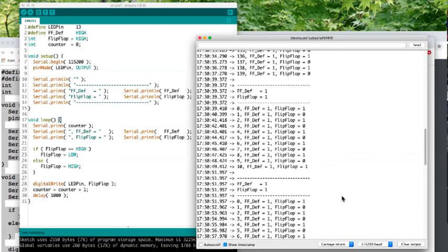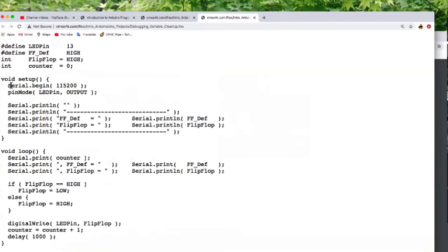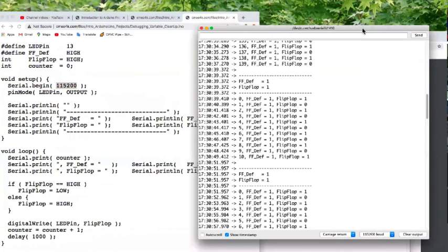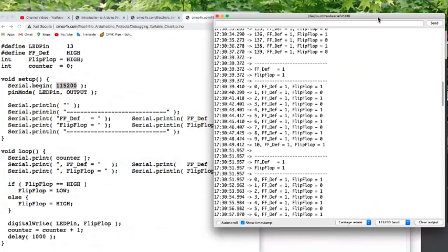That's just important. At the beginning, usually if you're seeing strange characters, it means the program is doing the setup, the initial baud rate. The program at the beginning says that I'm going to use my communication port, which uses the baud rate. This is the baud rate. The baud rate is a serial communication speed.